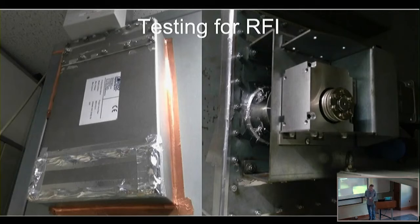And then, even though we've designed all of this, we test it, and we test it to death. So this picture is not very clear. We have a reverb chamber. It's kind of the opposite of an anechoic chamber. So there's a stirrer. This is the motor for the stirrer, and that stirrer rotates. The walls of the chamber are covered with a deliberately reflective material. And so you can excite all the different modes in this chamber in a very short time. So you don't know where signals are coming out, but you know if they're coming out.